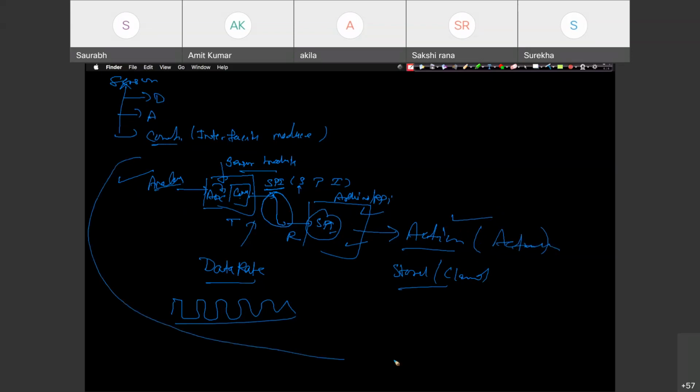So overall, what was this? It was an independent board having a component which receives your environmental parameter. Then that parameter goes inside a comparator or ADC, and then the ADC data gets communicated through a communicating protocol. For that protocol, there will be an IC sending the data to the external world. Either it could be SPI, I2C, whatsoever, depending upon the mode.